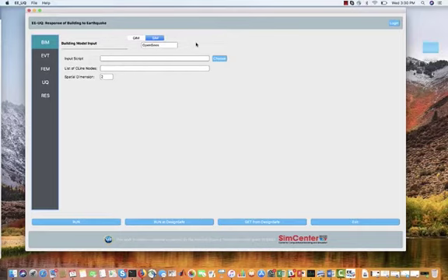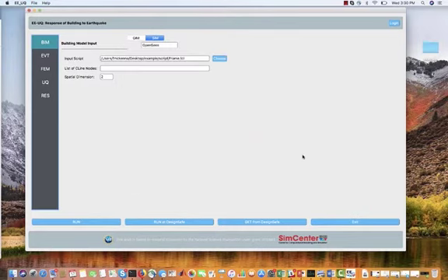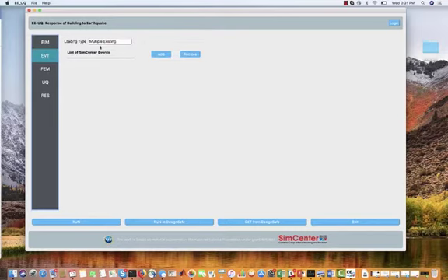For the OpenSees application, we specify the script which contains the commands to build a model, i.e. define the nodes and elements. It'll do a gravity analysis if we need and also define the mass for the building. So we're going to choose from an existing example. That example you have on your computers. It came with the application. So there's the example.